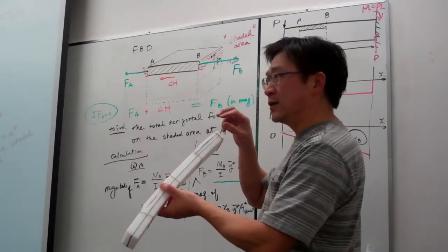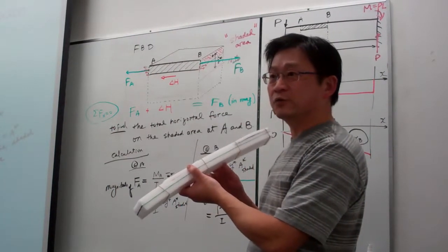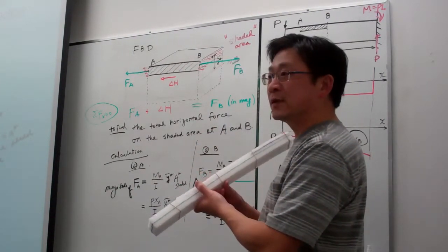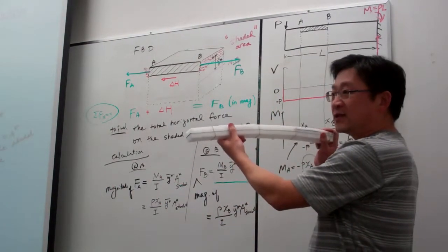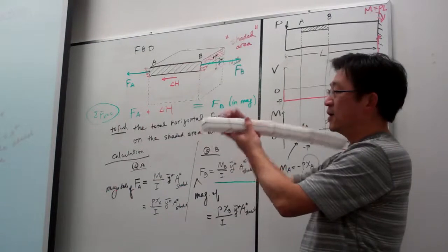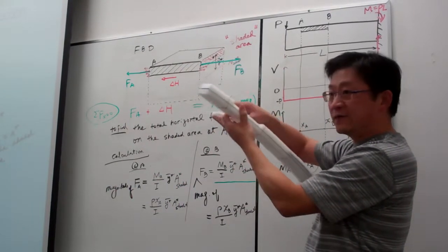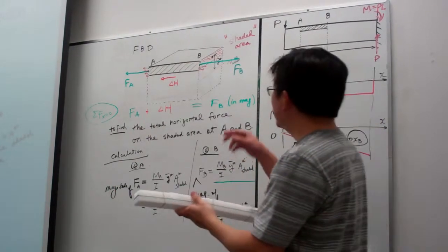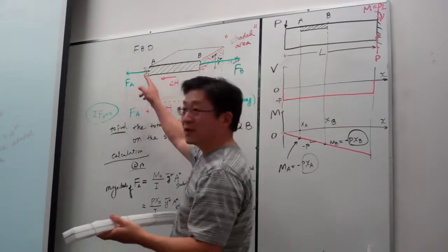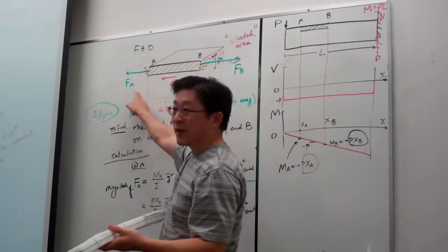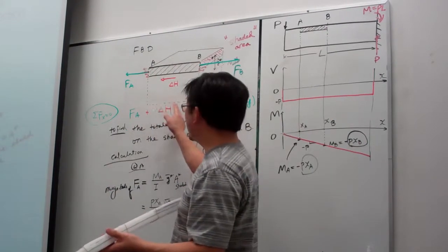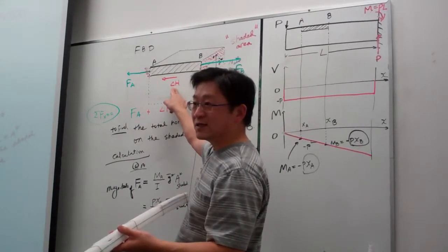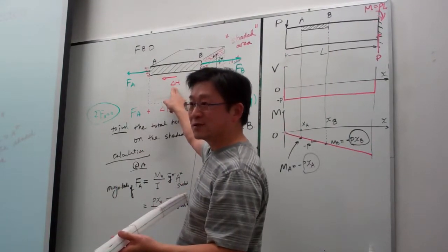This is a very straightforward analysis, and this is exactly the lecture our textbook talks about in I think 3 pages. I just mentioned asking you to preview last night. They exactly talk about the process here. Okay, and again, in a beam not under pure bending, we expect at each level they must have the reaction. However, in pure bending, the bending stress on the two sides will be equal. That means FB will be equal to FA. So in pure bending, do we expect delta H? That should be 0. So for pure bending, we don't see this kind of reaction force.